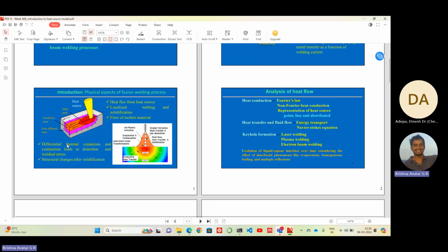Under some intense loading, it may try to reorganize, so it could just fail. That's why we always like structures with no such residual stress or strain. We want to remove it. Residual strain is fine, but residual stress leads to problems, because the body will try to do away with that stress.